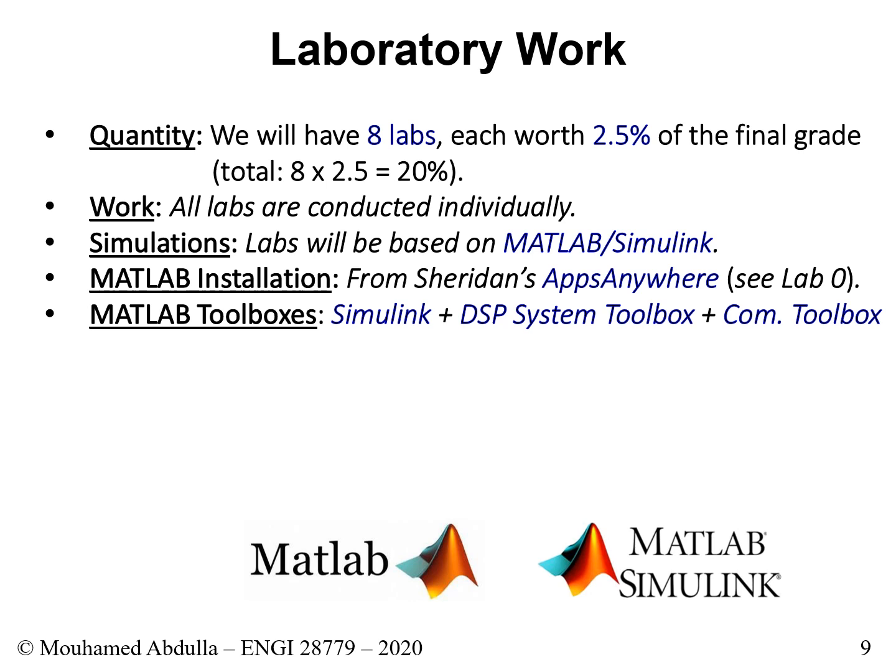Once you download MATLAB, at some point in the installation, it will ask you to select the toolboxes that you need in the installation. Just make sure that you select Simulink, DSP System Toolbox. DSP stands for Digital Signal Processing, and the Communication Toolbox. So make sure you put a check mark next to these 3 toolboxes. These toolboxes are the different applications within MATLAB that we will utilize, right? So Simulink is part of MATLAB, and MATLAB is kind of the main application.